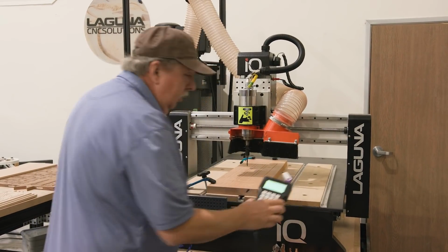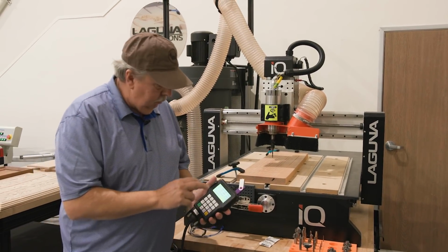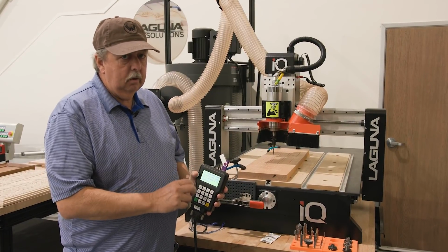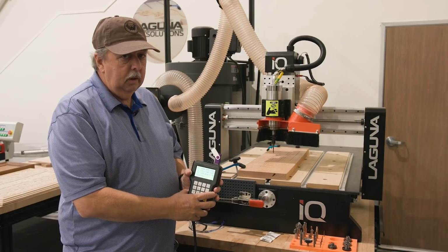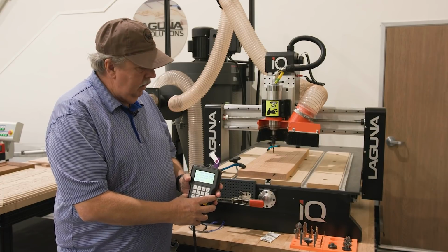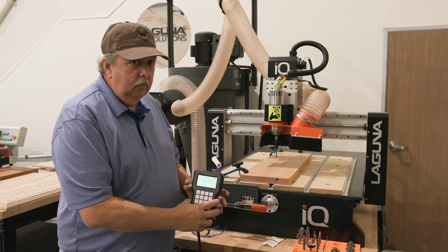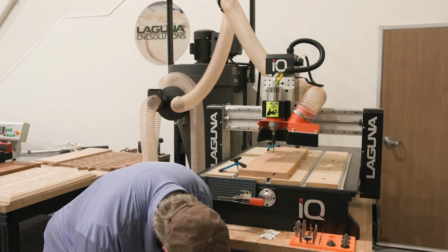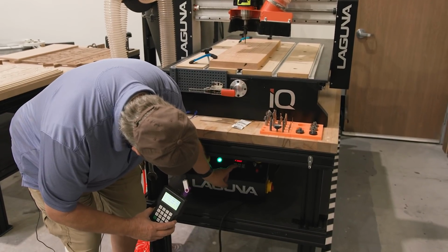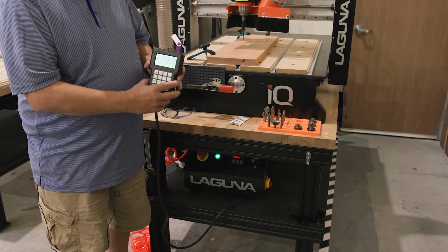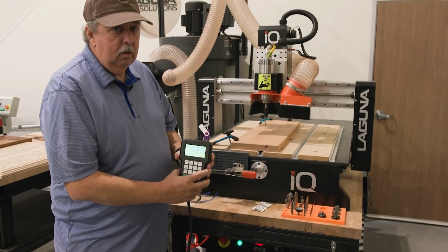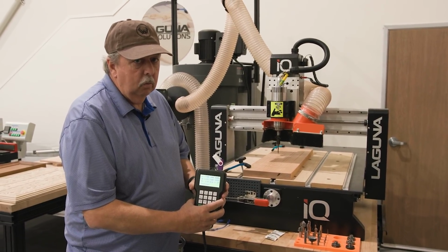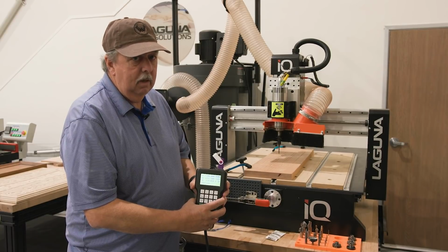So one other thing we have to do with this bit is we need to take the RPM down to about 10,000, then we'll monitor from there. But that's the recommended drilling speed for this type of bit. And that's something we haven't shown before, but we need to do. To do that, you need to take the VFD controller down here, and there's an up button and a down button, and you need to move that to the equivalent of 10,000 RPM, which is 166.67 or 167 in that area.